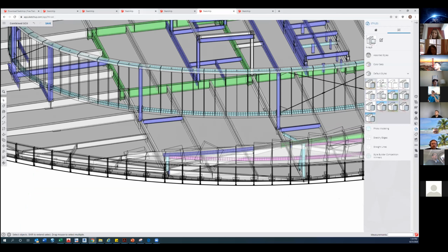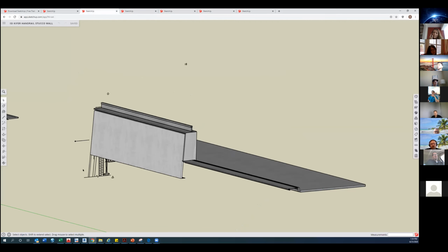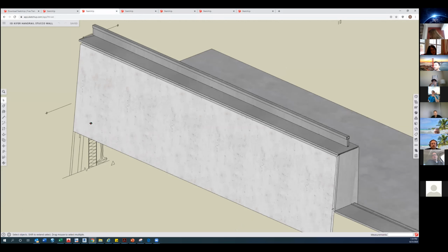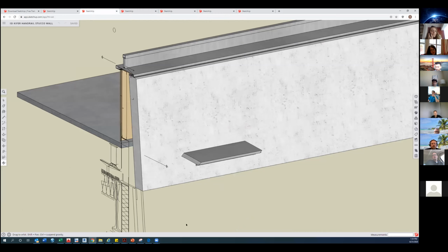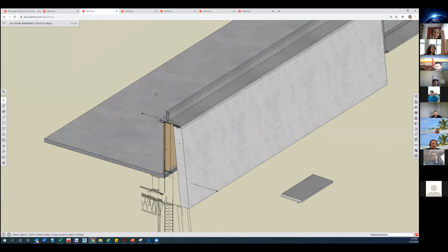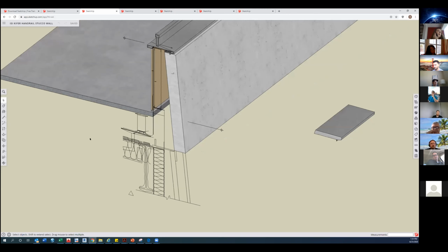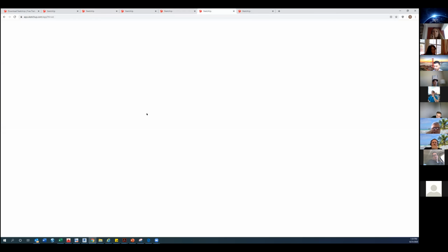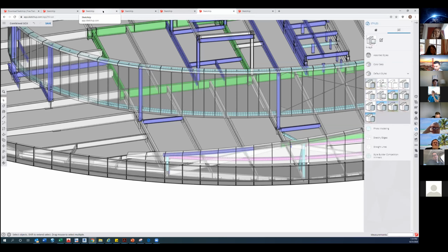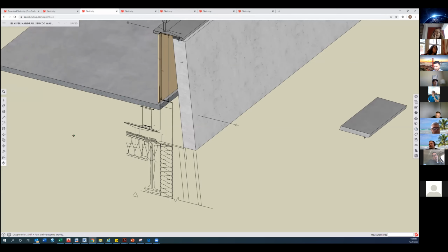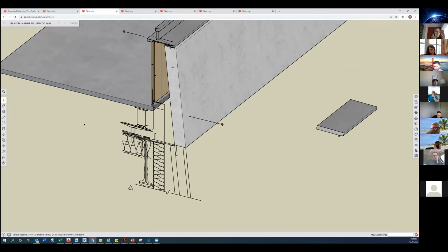And then, okay, because then you also said this is the Stevens Creek SketchUp model or whatever. Did the customer give that to you, or did you create that yourself from something that we made? Did you export our Revit model or make it yourself? Correct. That's exactly what I did. So it's just a matter of either doing it yourself or just asking the drafter. You export the Revit model into a 3D CAD model, and then SketchUp is able to convert that into what you see. So it's not from Revit directly, it's all from CAD. So our drafting exports to 3D CAD, or you just get a CAD file, and SketchUp reads CAD? Correct. Okay.